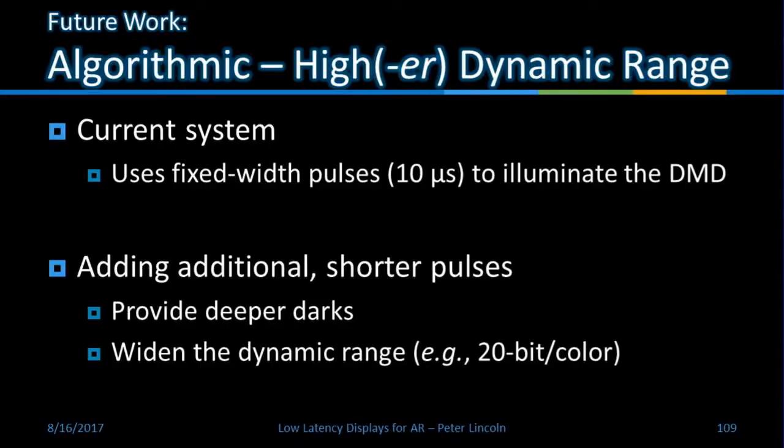16 bits of high dynamic range is nice, but for that photograph I showed in the meeting room, it's not quite enough. The current system used fixed width pulses to illuminate the DMD, and 10 microseconds was the longest pulse we could put in there before it would start interfering with the mirrors changing on the next frame.